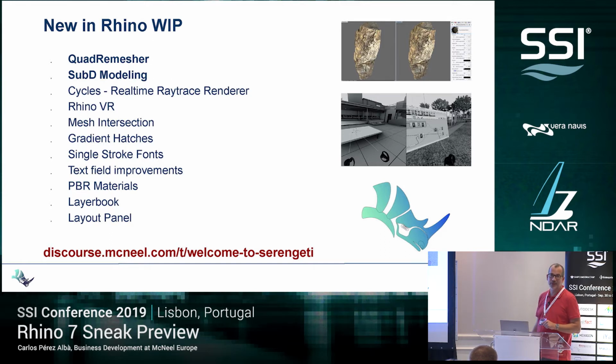There is a new mesh intersector, much more powerful, and also we can now detect if there are duplicate faces, etc. Because, well, we see, Rhino is a NURBS modeler, but we've seen many of our users working with meshes, both repairing meshes, editing, and preparing objects for FEA or CFD, etc.